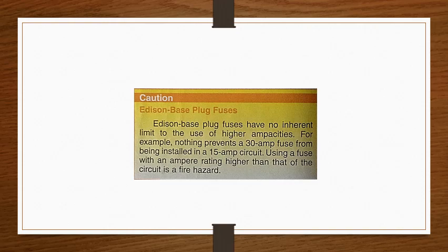Cartridge fuses. Cartridge fuses are used in fuse systems over 120 volts or 30 amps. There are 2 types of cartridge fuse connections: ferrule type and knife blade type.